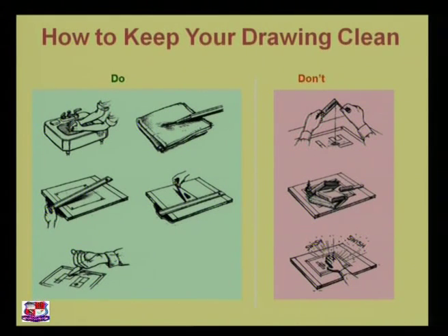Some of you are still not using the proper pencil. In the previous lectures, we have seen that in engineering graphics we must use H, 2H, 3H or 4H pencils. H represents the lightness and the toughness of our pencil lead.